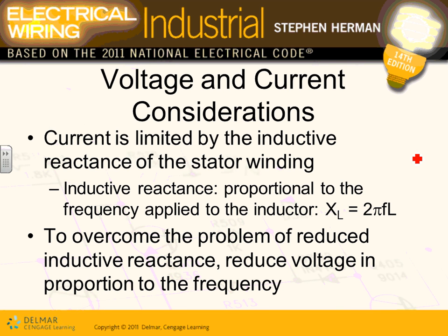So a few things about the VFD, guys. The problem with the VFD is that if you reduce the frequency, you will reduce the impedance of the coils, which increases the current in the coils. It reduces the inductive reactance, so that will increase the current. The current will go up.